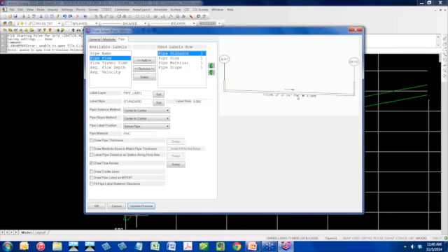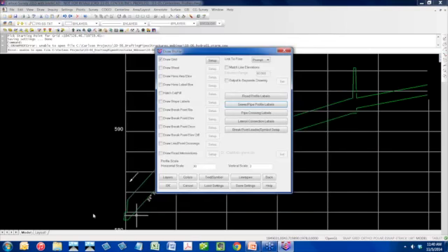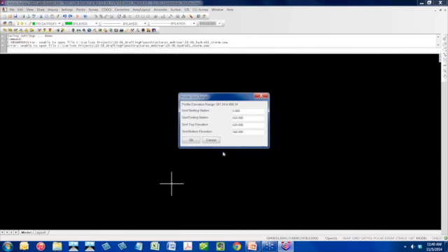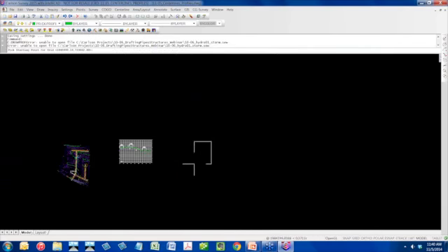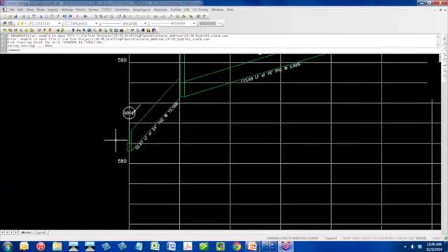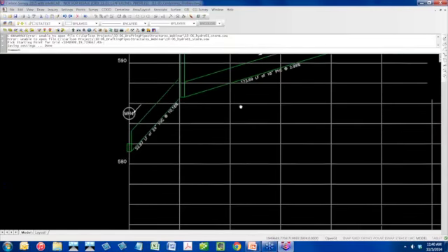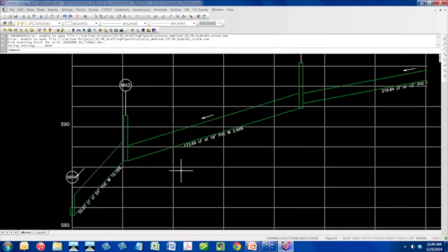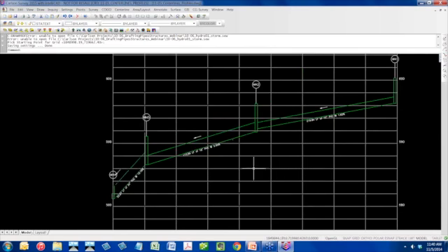125 linear feet, a 24-inch PVC at 4. So the 24-inch, the PVC, the 4%, that's just placeholder text. Pick OK, pick OK. We're going to redraw this. And ta-da. Nah, my arrows up here, probably don't want that. But you kind of get the idea. Again, this PRO file was actually generated and exported from hydrology, so that makes it kind of easy.